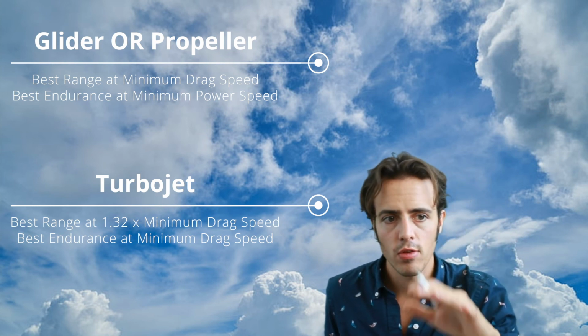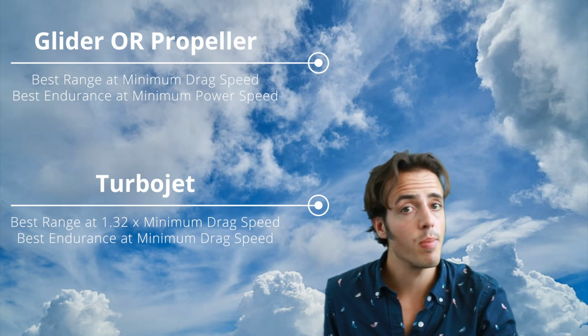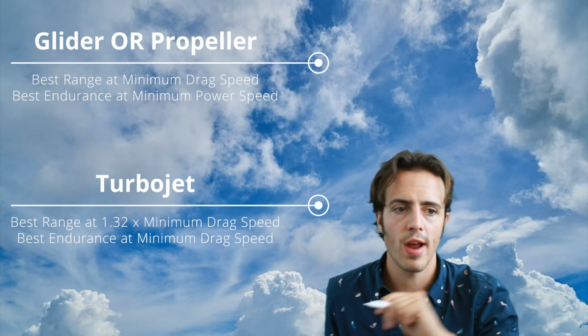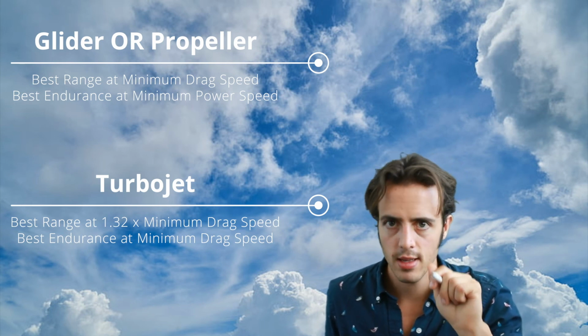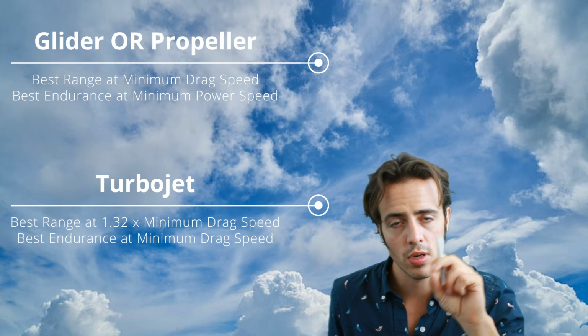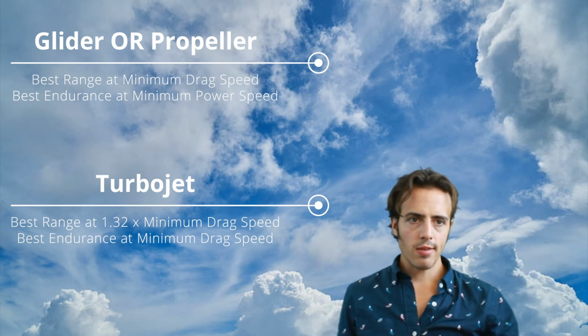Range is slightly different. So range for a glider is found at the minimum drag speed, and it's the same for a propeller aircraft, found at the minimum drag speed. For a jet aircraft, this is at some speed that's greater than the minimum drag speed, and it's that proportion 1.32.